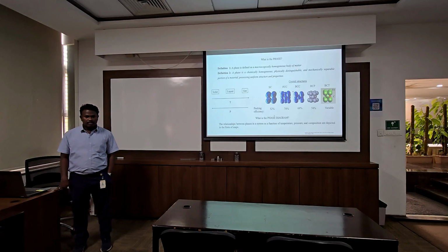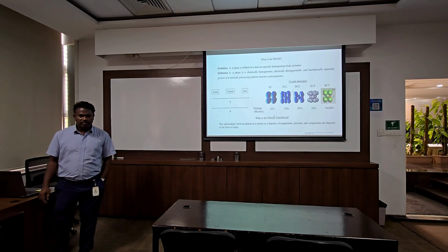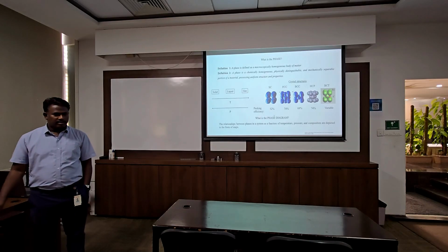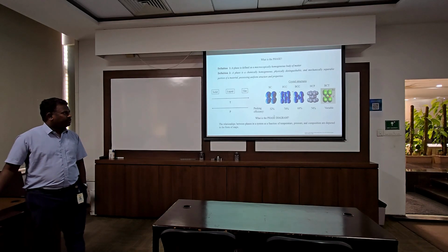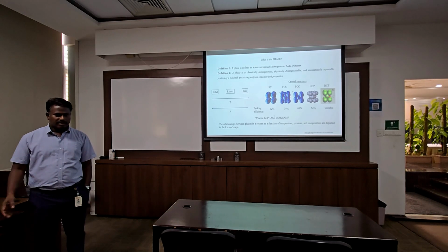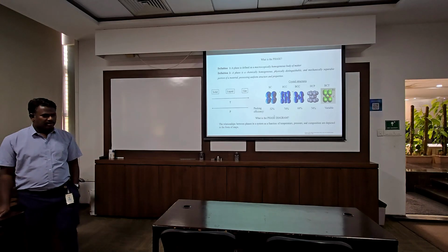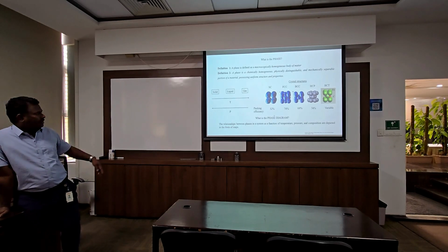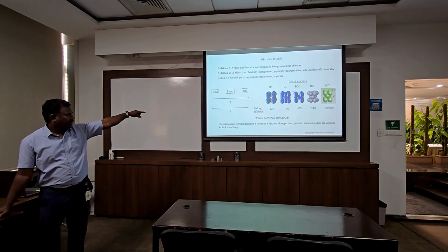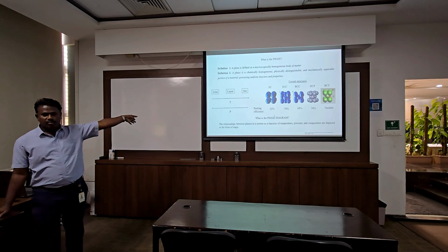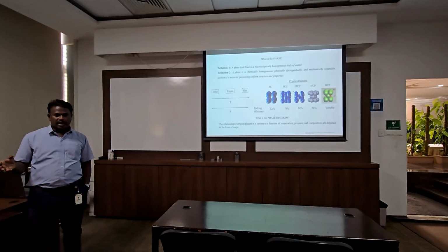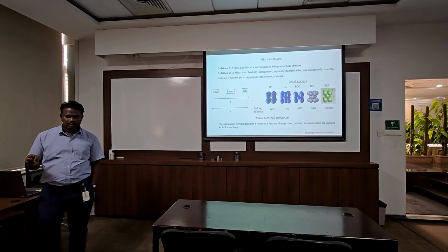Simple cubic will not be stable at room temperature, because of the voids and the expansion of volume. So the density is very low, and the packing efficiency is 52. As a basic law, at low temperature we should have high packing density, so atoms should be closer.